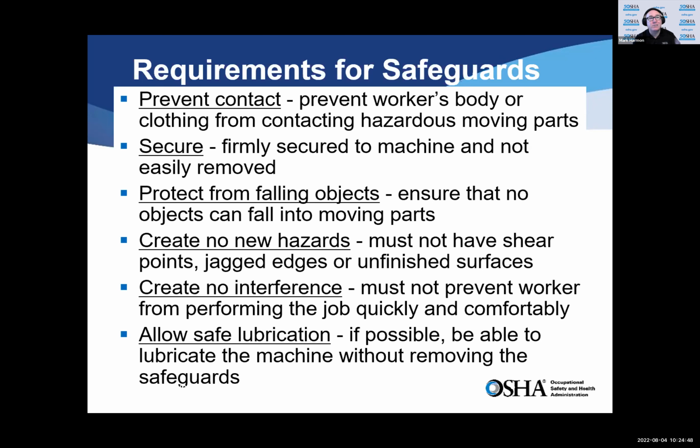How can I build this so that my maintenance crew aren't putting themselves in such a position, especially if you're just greasing the machine with a grease gun? Okay, well, try to make it so that the grease fittings are accessible. Don't have the employee climbing all over the machine simply in order to service it.